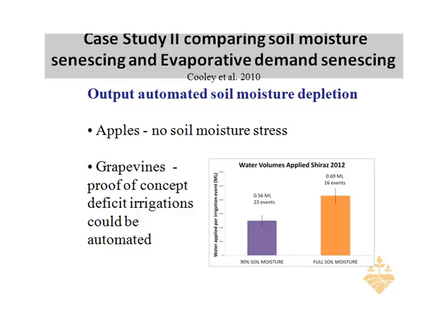Different crops require different soil moisture depletion categories. For example, apples operate best if they don't experience water stress, while during periods of growth grapevines produce a better composition of their berries if they do receive a deficit irrigation. So we address the question, could deficit irrigations be applied using this technology?